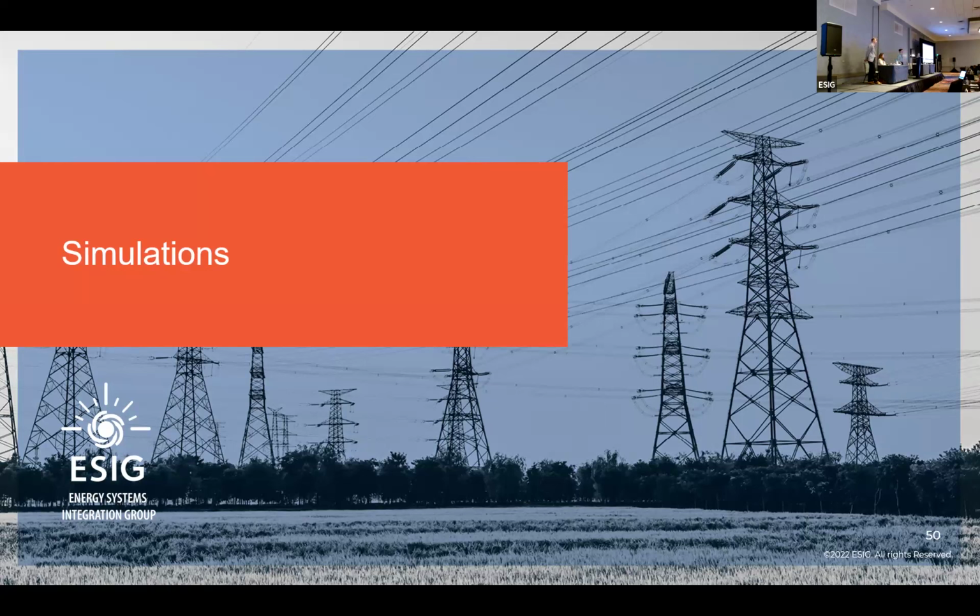We know that the system operator is gathering these EMT models, but with which accuracy is correct? There are at least two main methods: average modeling, which is faster, and detailed switching of the legs, which is slower but maybe more accurate on the DC side.